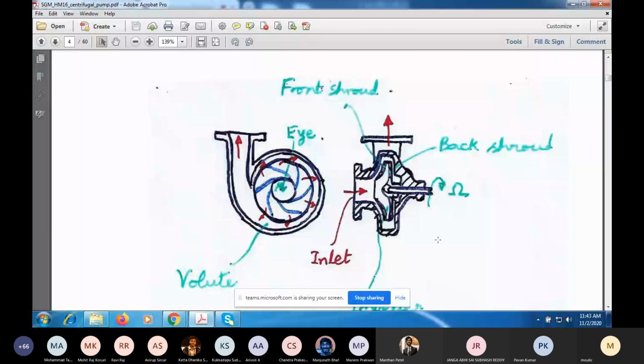So look at this. Okay, these are two engineering diagrams. So on the left hand side, this small circle here is called the eye of the impeller. So the fluid, when the pump runs, will enter the pump through this eye, and the liquid will enter in the direction perpendicular to the plane of your screen. Okay. So this is your impeller. So the blades of the impeller are between this small black circle and this outer black circle. Okay. And these blades are shown in blue.